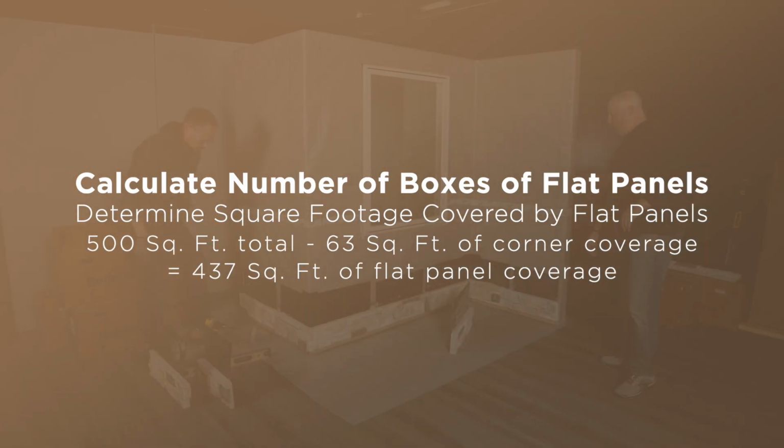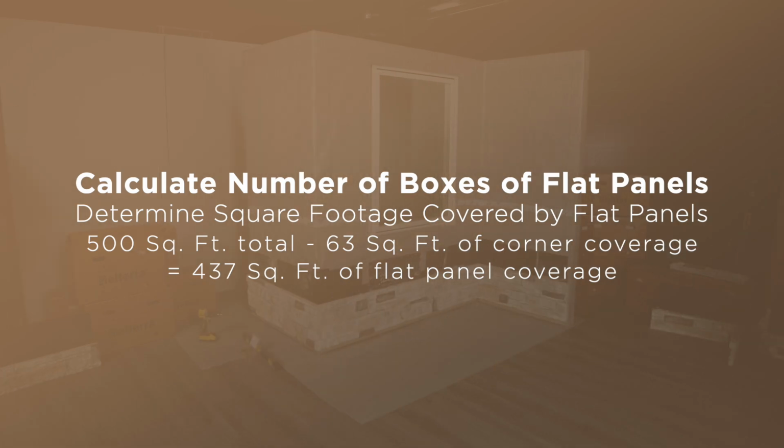Determine the square footage to be covered by flat panels. Subtracting the corner coverage, 63 square feet, from the total square footage of the project, 500 square feet, will provide the surface area to be covered by the flat panels. 500 square feet total minus 63 square feet of corner coverage equals 437 square feet of flat panel coverage.